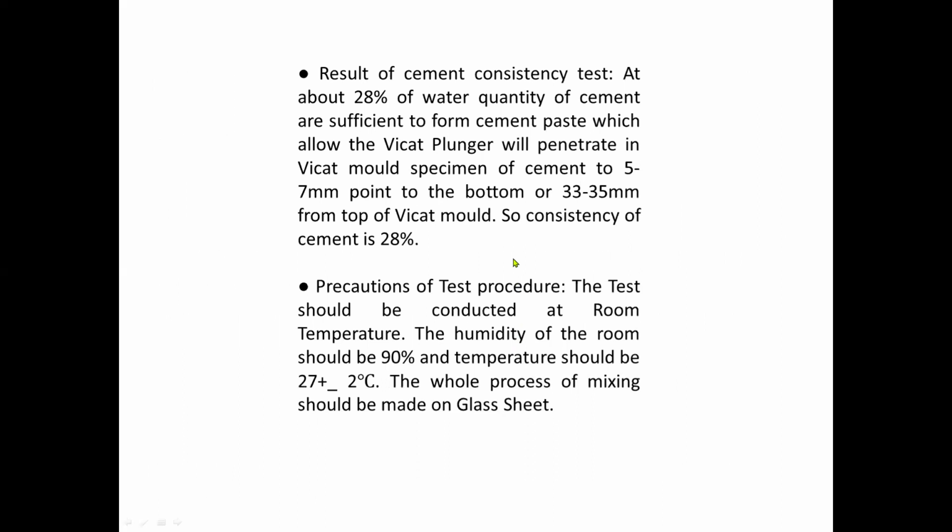The precautions of the test procedure. The test should be conducted at room temperature. The humidity of the room should be 90% and temperature should be 27 plus or minus 2 degrees Celsius. The process of mixing should be done on a glass sheet.